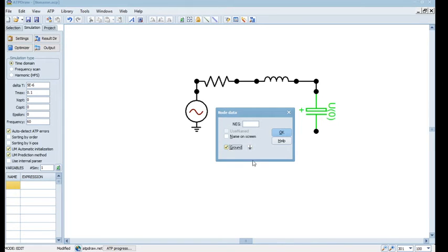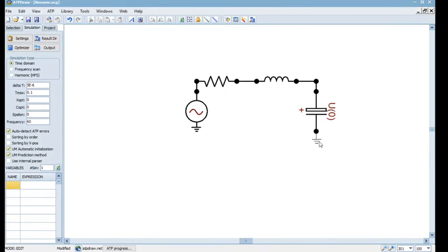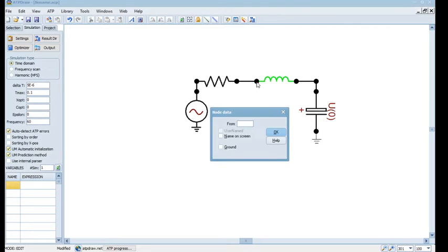So it just grounds it. To suit the orientation of the ground symbol, you can click on this symbol also: up, then left, then right, and then bottom again. So I'll say okay, and it just gets grounded. The same thing you can do with any node, for example, here. And in fact, we will be using this block. We'll come to that shortly.